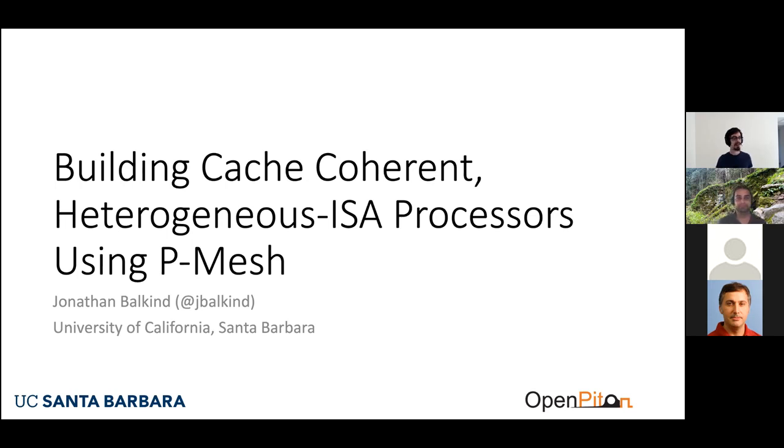So we basically provide a guarantee of TSO on what we call a memory thread, basically one port into the private cache that we provide. If you want something stronger than TSO, you can fence your core in the right way to not send requests into the system in such a way that TSO is too weak for you. If you want something weaker, to get more performance, you can make use of multiple memory threads. This is what they did with Ariane. Then you can keep track of the metadata in your core to make sure that you respect your consistency model in the right way. We talk about this a little bit more in the paper, but that's the high level gist.